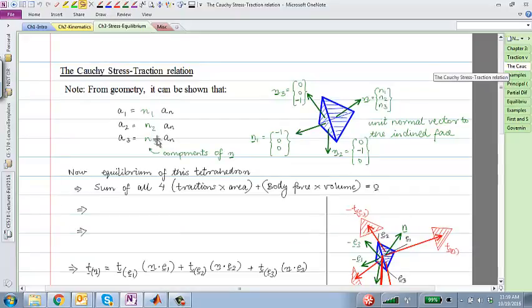And in order to do sum of forces, we are going to use three geometrical identities essentially. If I have a right angled tetrahedron like this, the one that I've shown, then you can correlate the areas of each of those four faces using the components of the normal vector of that inclined face.